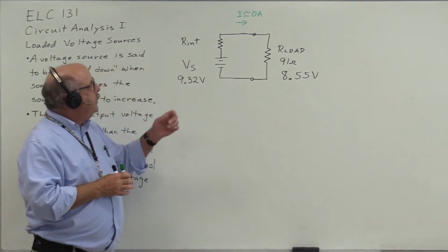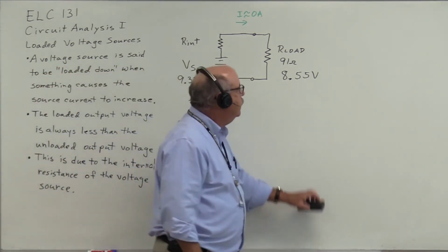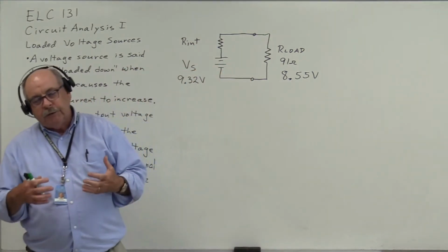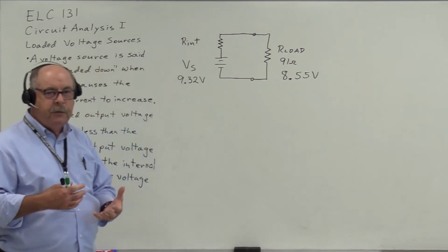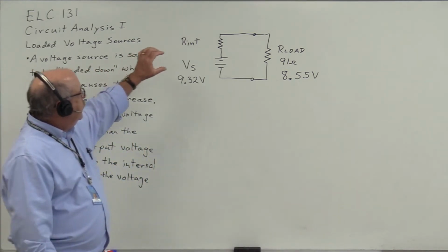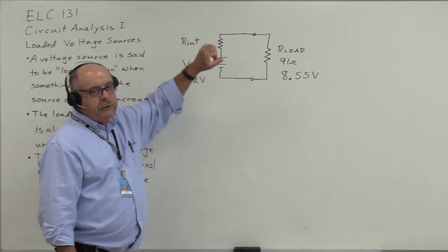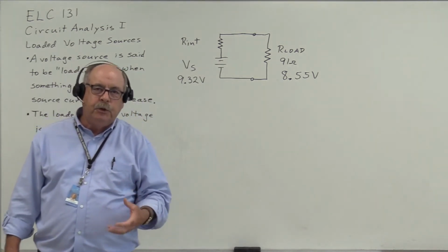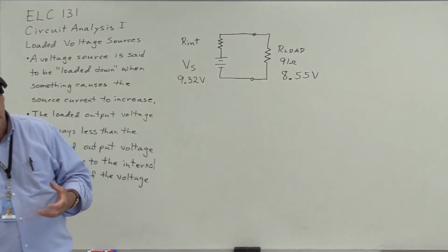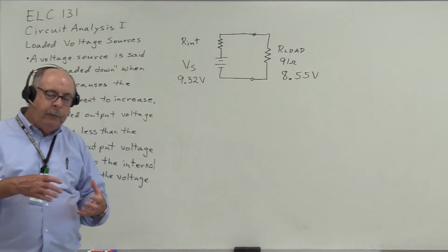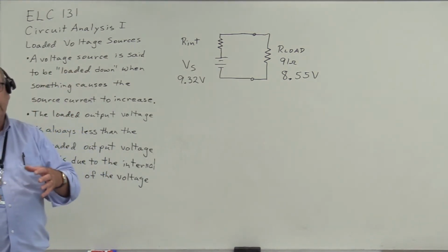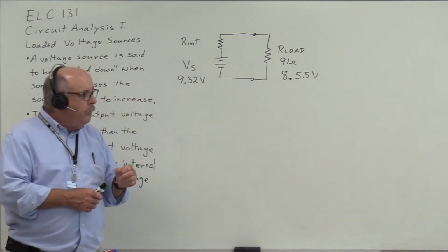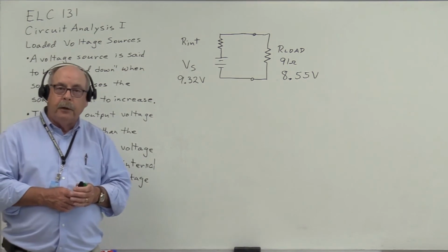Now, the question is, how do we determine the value of the internal resistance? Because this is not something we can measure with the ohm meter. In this battery, the internal resistance is really a layer of H2 molecules, hydrogen gas bubbles, that are formed by the chemical action or reaction inside the battery. It's not something we can measure, but we can determine this empirically.